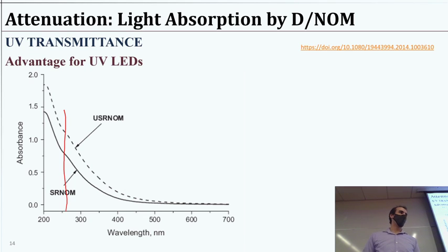And the point here is that random organic matter in your samples, whether that's from natural sources, or maybe it's a wastewater effluent that's got a bunch of junk in it, the UV transmittance is going to be relatively low through the water. Like that laser pen picture that we saw, it was not transmitting more than a few centimeters through that liquid because it was full of this dye or whatever. So you can imagine high strength wastewater is going to be the same deal. A lot of organics. That stuff absorbs, especially in the UV. Now, visibly, we maybe only see a little tint of a brown or greenish color or something. In the UV, there's all sorts of molecules that are absorbing.